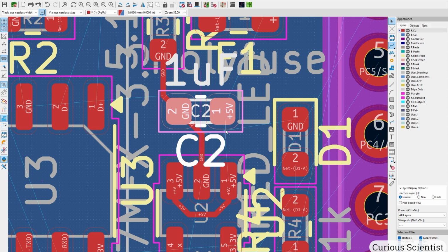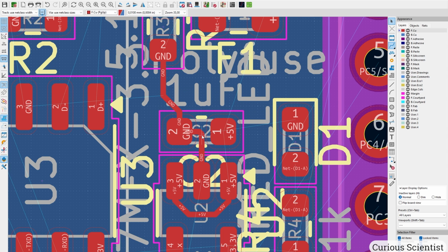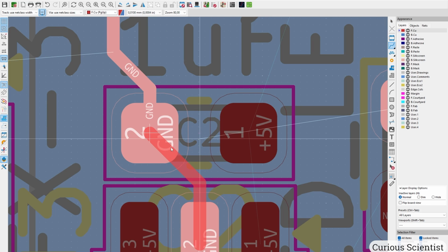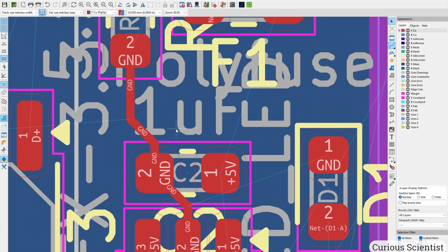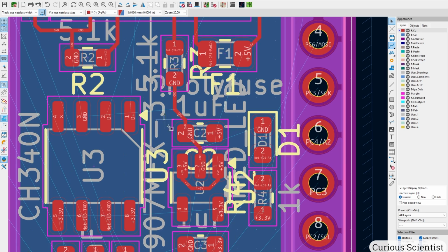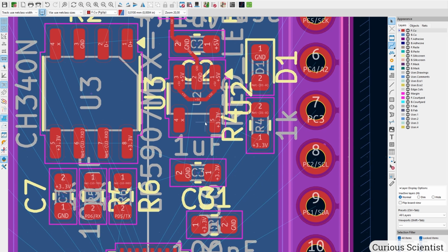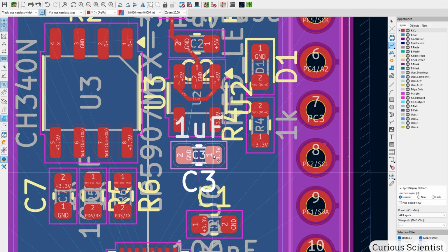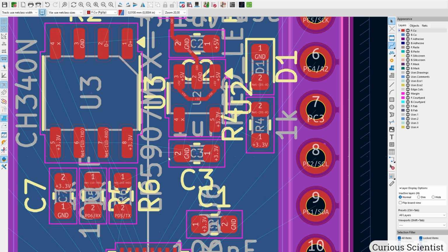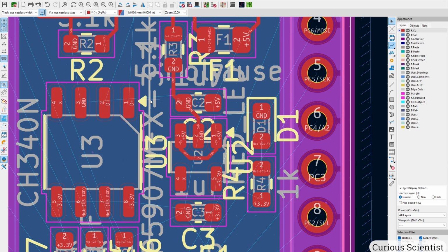And since we have this, I can come much closer here. And by pressing D at this corner, I can route a bit probably nicer. So they can go a bit higher up here, something like this. And then I just remove the excess trace. And this can also follow it, something like this. So now we have a corridor here for traces if we need it.